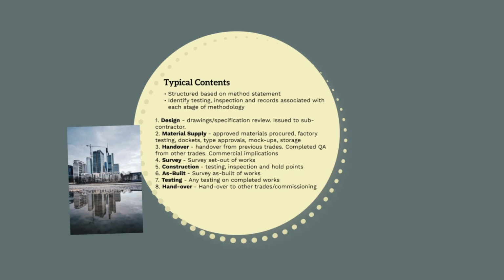We'll also need surveyors to mark out the works providing heights, dimensions, and any additional information from the design. It is critical to ensure that the works are set out correctly and that the surveyors are using the correct set out files. Once all of these checks are complete, construction can commence. This will require detailing any testing and inspection required, depending on the construction methodology and relevant specifications. Any hold, witness, and inspection points will need to be identified.